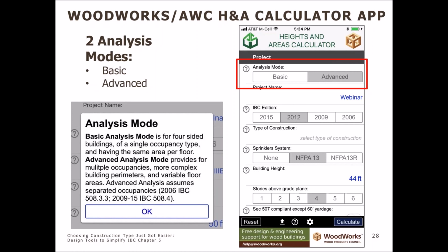Great. And have you come across where a design team has come to you and they're doing actually a Type 3 building on top of a podium, but really they could get away with a Type 5, and the calculator could help realize this? Yeah, absolutely. I think that's very common. 4 over 1 type buildings are very common, but you're absolutely correct that a 5-story Type 3 building could be a very viable alternative. So if someone were to use the calculator and just say, I have this 5-story building, can I make it work without a podium? The calculator could definitely determine that.